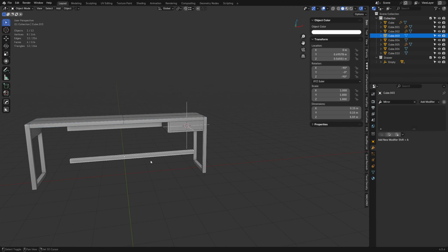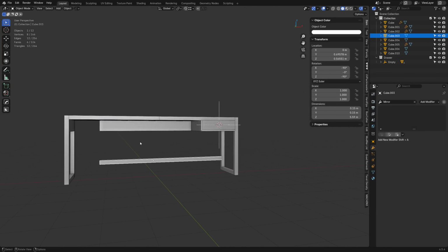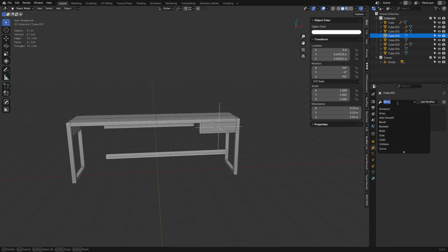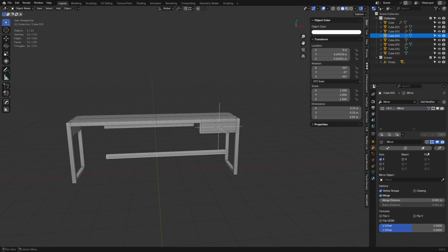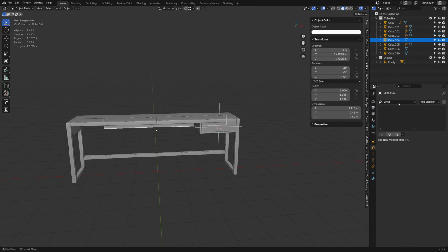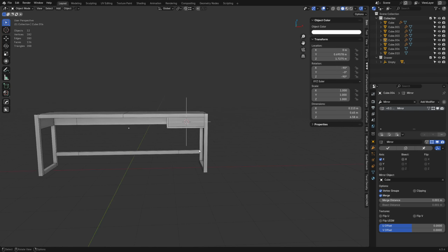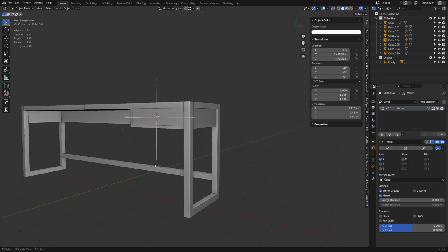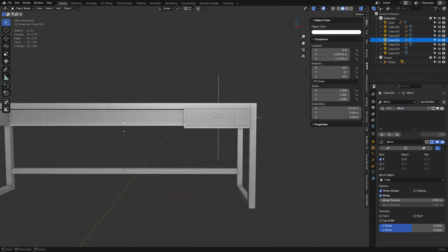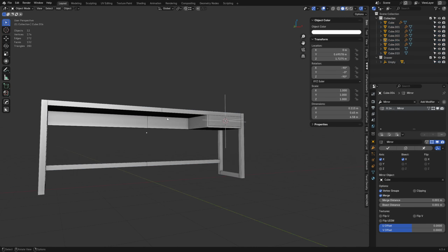Overall, I'd say we're pretty good. Obviously, these ones back here, not so great. Once again, if you want to do everything on one side of the model and mirror it, you can do that. There's nothing inherently wrong with that. So mirror modifiers here do work, but now we'll have to clean up those center lines later on, perhaps. We also want to make sure that we bisect anything that crosses over itself. Otherwise, we end up with double faces in the middle there. That's usually not ideal or what you want.